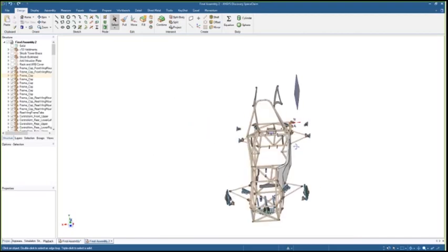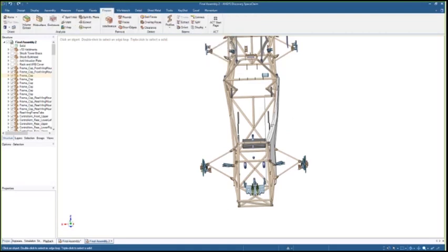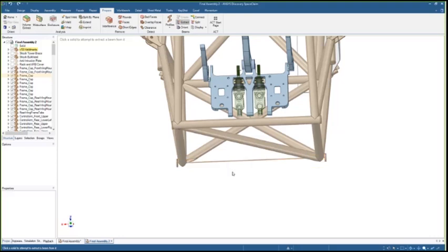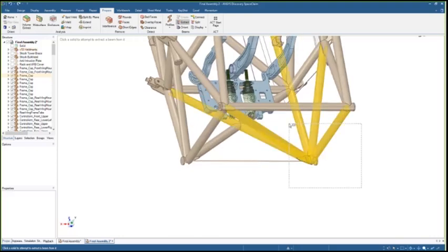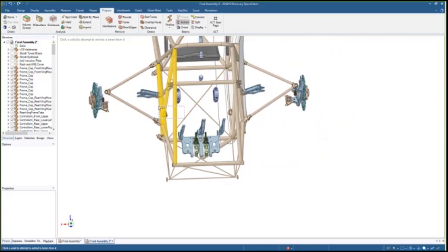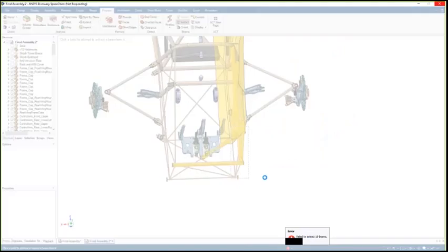So the same way that I was extracting mid-surfaces from the model, I can also extract beam elements. The beam elements are going to save the cross-sectional profile, and so all I have to do is turn on this extract tool, and notice that if I click one beam element, or one solid, I get a beam. If I drag a box across a few, it'll do those. So one method is to select everything. If I were to go through and hide everything that wasn't a beam, I would box select everything. But because there are so many more other elements than beams, it's going to be a little easier to select it this way. Now, I should have hidden that fairing on the side here. It's trying to extract from the fairing, which it obviously cannot do.